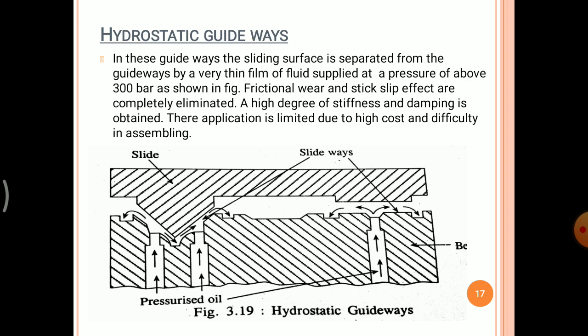The frictional wear and stick slip effect, which we have already discussed, are completely eliminated in the hydrostatic guideways. A high degree of stiffness and damping is obtained in the hydrostatic guideways. The application of hydrostatic guideways is limited because of its high cost and difficulty in assembling.